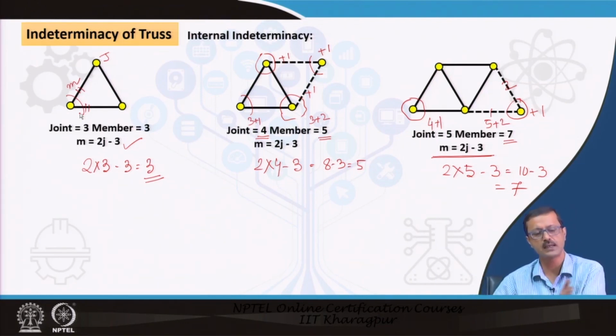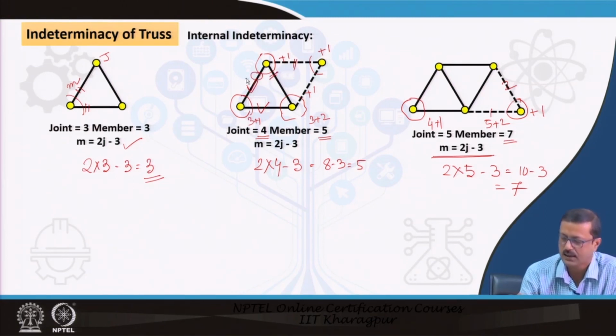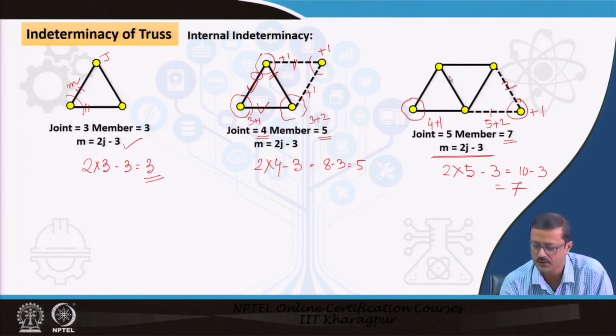So, if you proceed like this, after we solve this particular joint, this member force and this member force are known to me, then the next joint can be found, because these two are unknown and this is already known. We can also, if I know these 3, easily find these 2, because I also know this one.